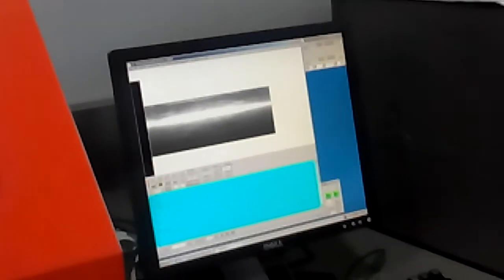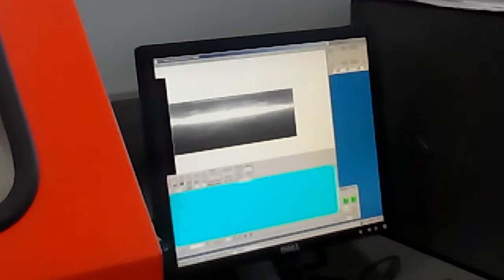Once the machine is connected, you have to switch on the spindle, but before you switch on the spindle, you have to do the home positioning. Every CNC machine we have to do home positions. Some machines we have to do initialization. In this machine we have to do home. The button is there, home is in here. Click on home, and we have 2 axes in this machine, so we have to home both axes. We are going to home the X axis first. Click on X and press OK, and then Z, press OK. So now we have done the home position.